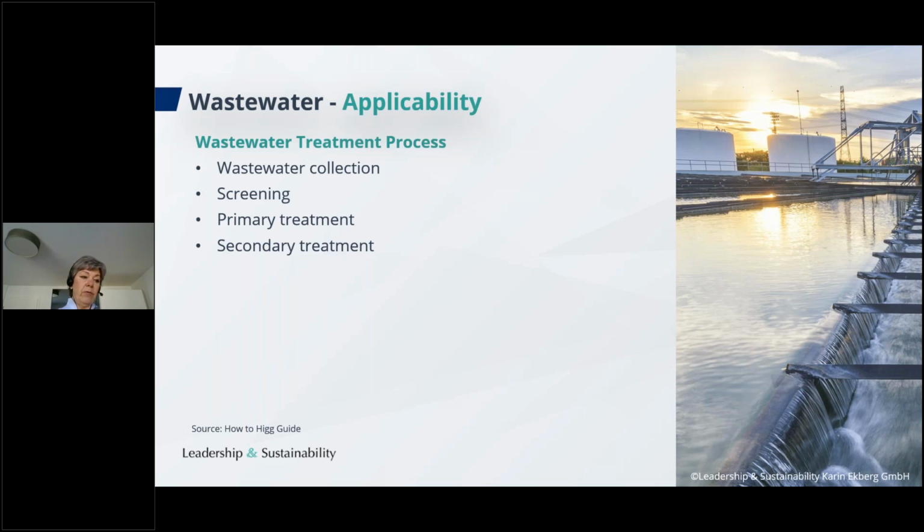This is done under aerobic conditions with the help of bacteria and microorganisms that consume organic matter. The process takes 3 to 6, perhaps even longer, hours, and results in the production of large particles that settle as sludge to the bottom of the tank. In addition to the application of activated sludge, the following steps can be included during the secondary treatment: aerated lagoons, as you can see here, for example, biofilm, trickling filtration, oxidation ditches, etc.